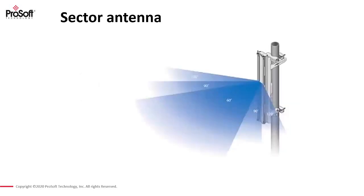And then the last type of antenna that I wanted to cover is called a sector antenna. If you travel around, you may see them on some of the mobile towers. They're generally tall, thin, upright antennas, and they'll have a wide beam that could be anywhere from about 90 degrees to about 140 degrees. The vertical beam isn't going to be that great, and they're designed for wide coverage. Those are your basic antenna types.